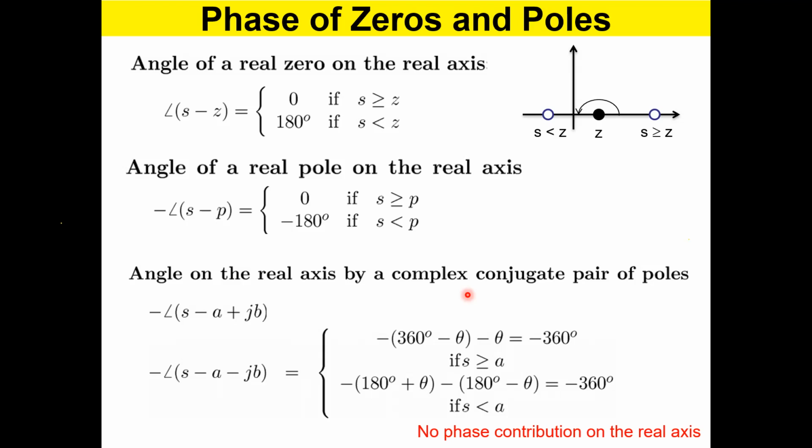Remember that case, a pair of complex conjugate poles, right? So similarly, that is an interesting point. When the two poles met on the real axis at some point, after that one goes north, one goes south. So there you can see the root locus is symmetric. If you have something above the real axis, you have the same thing below the real axis as well, right? Because of this complex conjugate nature of the poles.